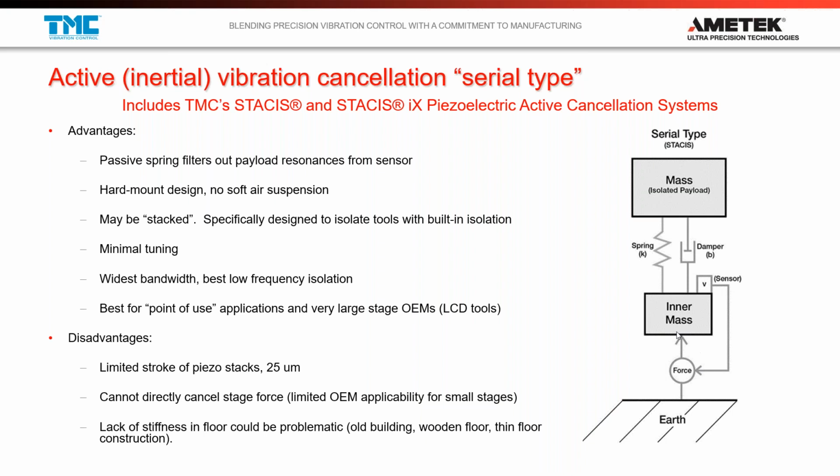Also, what's interesting is that our force actuator is a piezoelectric, a ceramic piezoelectric crystal, which is a device that will expand and contract in response to voltage that's applied to it. And what's so interesting about piezoelectrics is they, unlike a linear motor actuator, can be load bearing.